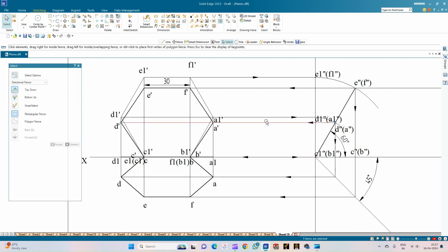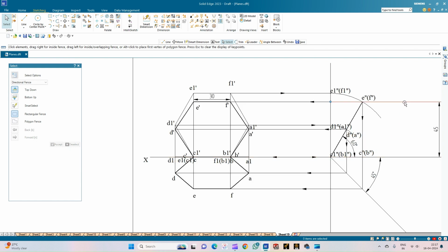So now we are going to draw the side view of the lamina in such a way that one of its edges, that is opposite to the edge on which it is resting, is at a distance of 45 mm. So we will draw the offset line, that is 45 mm from the HP, and then on this we are going to transfer this side view. So how do we do that? From the point of intersection of the x1 y1 line and the xy line, we are going to cut an arc of this length on this 45 mm line. So we will transfer this side view to this 45 mm line, and then this is the inclined position of the lamina with respect to the HP.